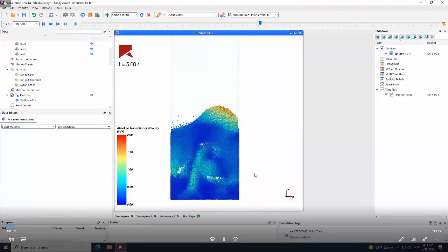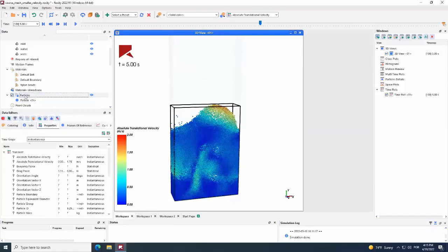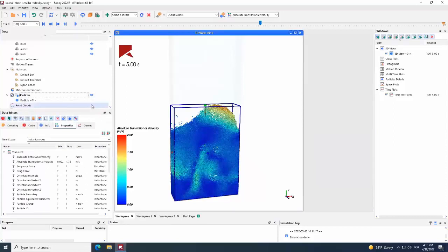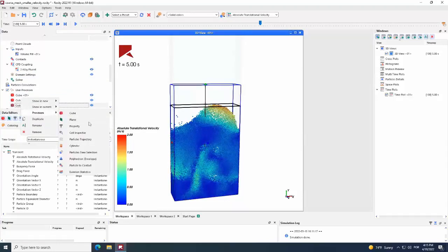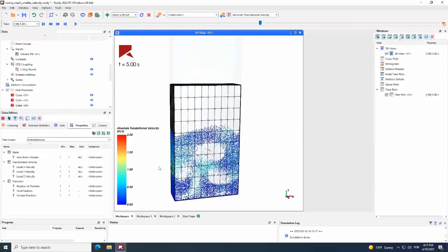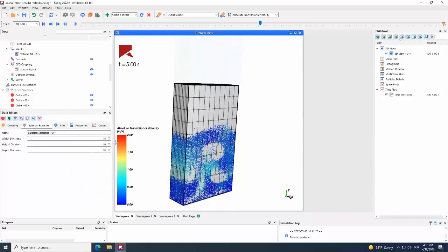So again, same fluidized bed results, showing information per particle. This time, let's convert this to an Eulerian vision, let's call it. Moving from discrete to Eulerian. I will create a cube here again. Let's make it a little bit bigger to encompass particles. And for this cube, I can right-click and create a process called Eulerian statistics. This Eulerian statistics will subdivide this cube into a certain number of regions, and you can change this, of course. So in this case, let's change to 3 divisions.